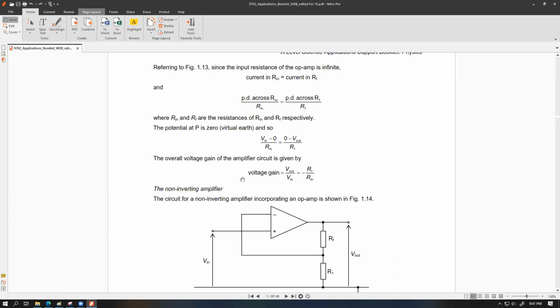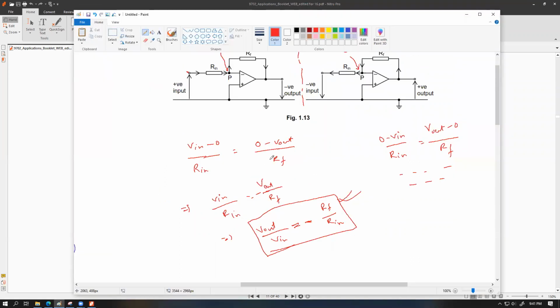So this is the key equation for the working of the inverting amplifier. Now, important information for you to see. Have a very good look. This has become our new gain, right? For this feedback mechanism, do you see any presence of the A naught over here? The original A naught or the open loop gain that we are talking about. Do you see any mention of this thing?